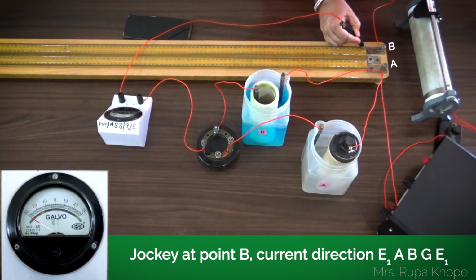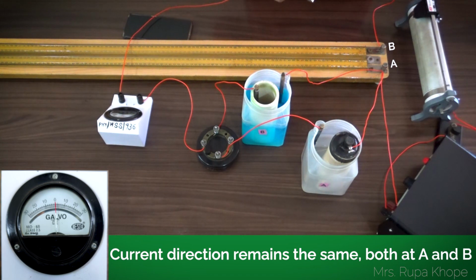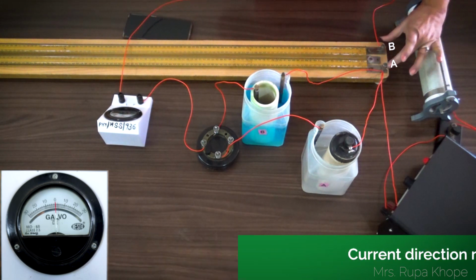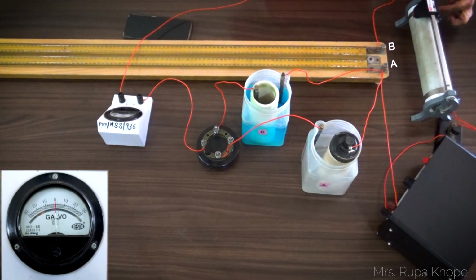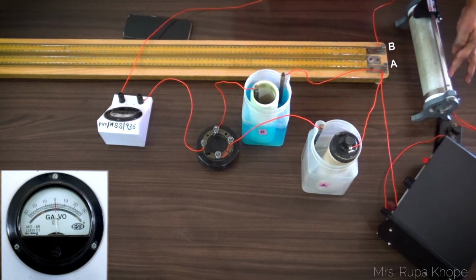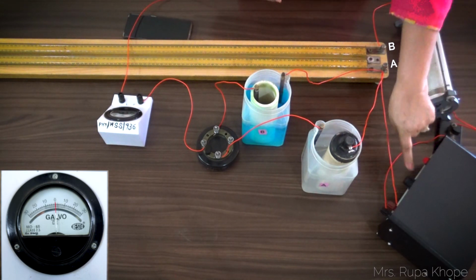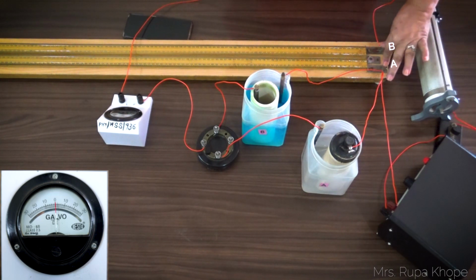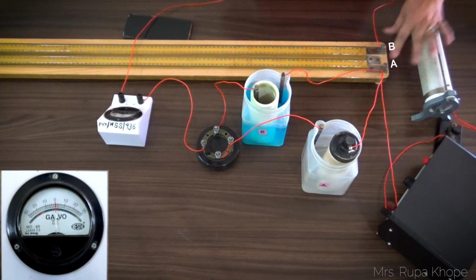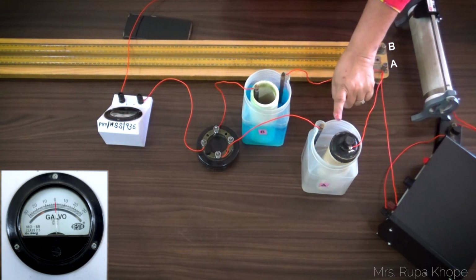Now here also it is 0, meaning it is on one side. So what is your inference? It means the voltage drop across this is very less. You can see that this rheostat is fully in the picture, full connection. So our whole wire is in the picture. Whatever voltage drop, 6 volts, the maximum is dropped across the rheostat and very less is dropped across AB. Therefore, in this case, VAB is very, very small, much less than this.